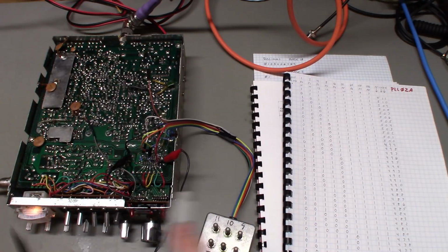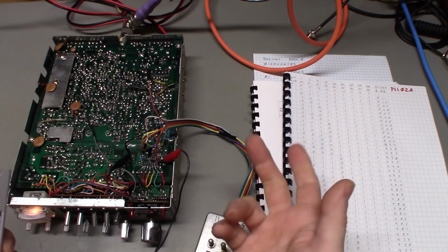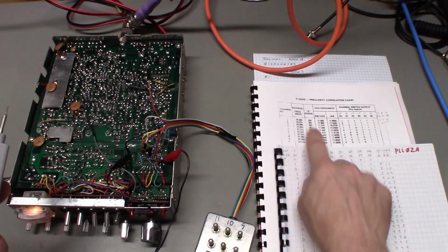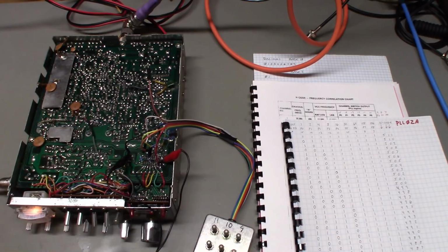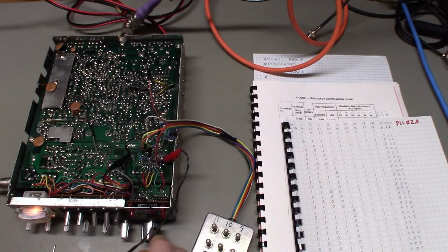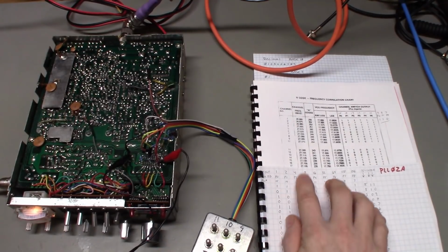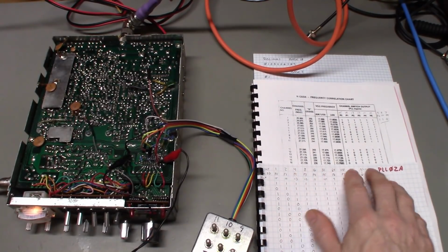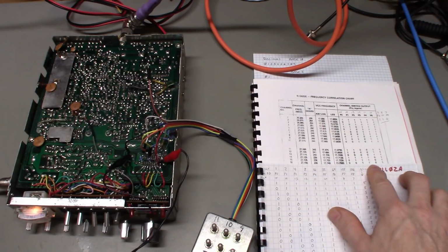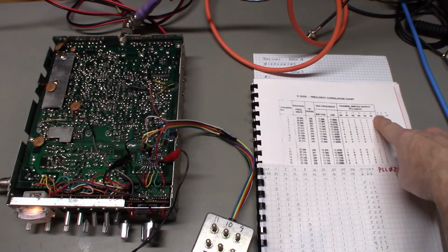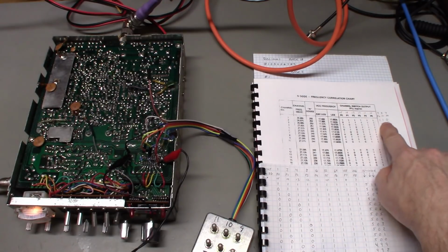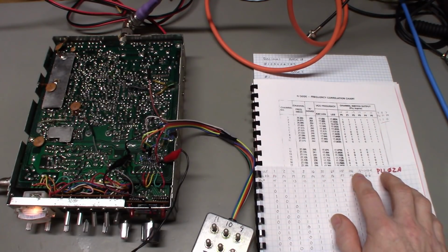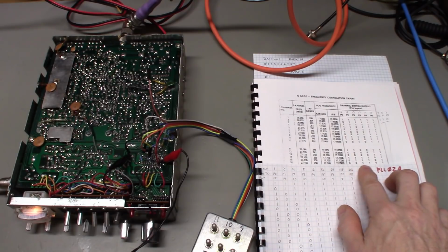And then what you can do is take your radio, put it on, pick a channel. Usually you'd start with channel 1, but put the radio on channel 1. You just take your logic probe, or let's say, actually, what am I on here? And yeah, there's missing digits on this display. This is actually channel 16. So if we go down to channel 16 here, we can see we should have 00, 11, 01, and then remember, these last 3 digits just carry down because they never change state. So it'd be 110. So the first 4 should be 0011.